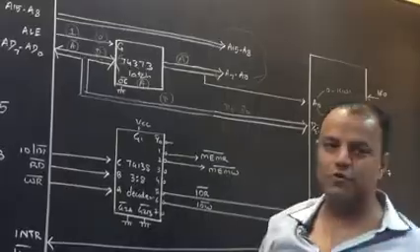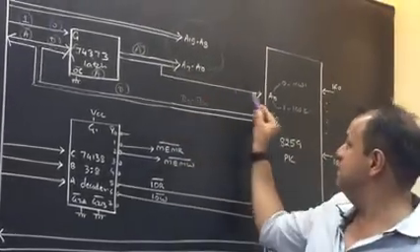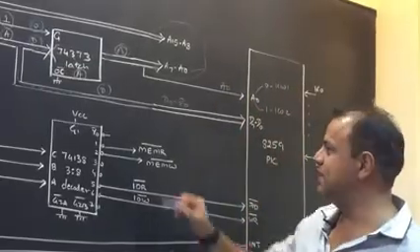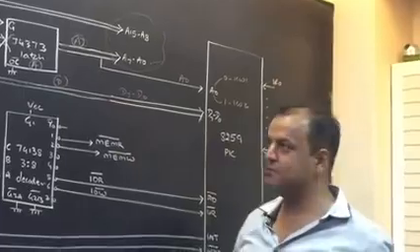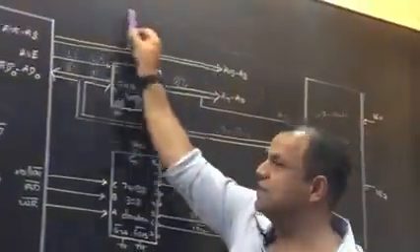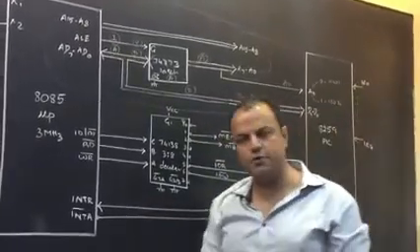So this becomes your full address bus, A0 to A15, out of which we will be connecting A0 over here to identify whether it's ICW1 or ICW2. We'll be connecting the data bus over here. Please tell me, is this whole upper part of the connection clear? Tell me, did you understand it? If I ask you to draw it again by yourself, will you be able to draw it?